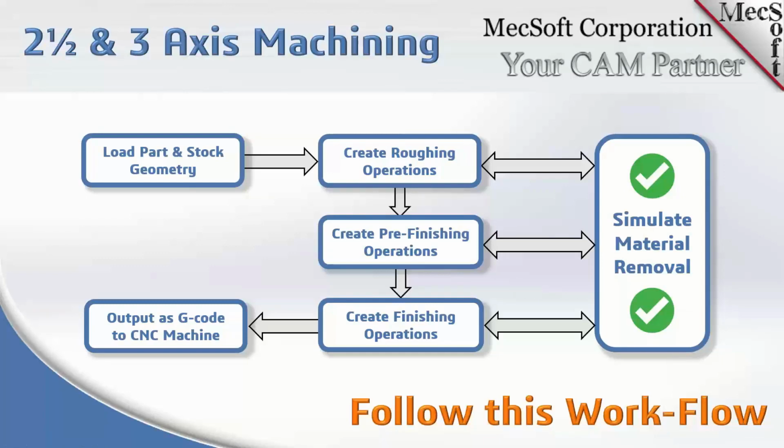And there's some users who get comfortable using the product and they decide that they don't need to do a simulation. Well, I'm going to tell you, you need to do one every single time. Even if you understand what's going to happen and it's not really complicated, it will highlight areas that you may not have thought about, and it'll protect you from possibly damaging a tool or some stock.